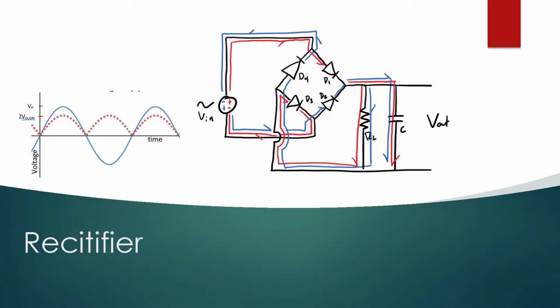voltage. This current then flows through the resistors and capacitors, that I'll talk about later. It then enters D3 and returns to the power source. A similar path is followed with the negative portion of the AC signal, shown in blue. The current flows out of the source into D2, through the RC circuit, and through D4. It then re-enters the source. This results in only a positive voltage output, regardless of its sinusoidal nature in the input.